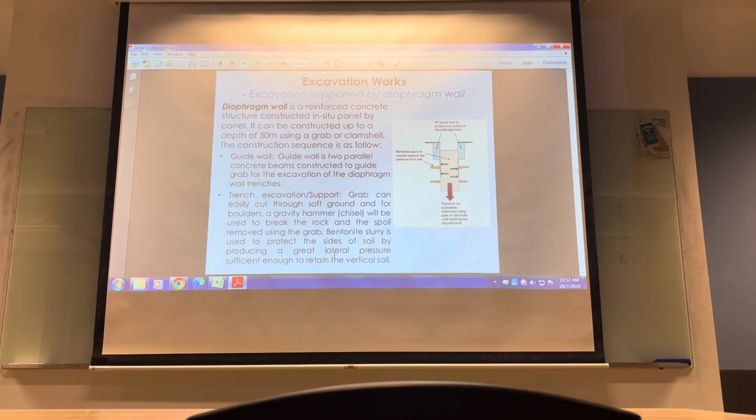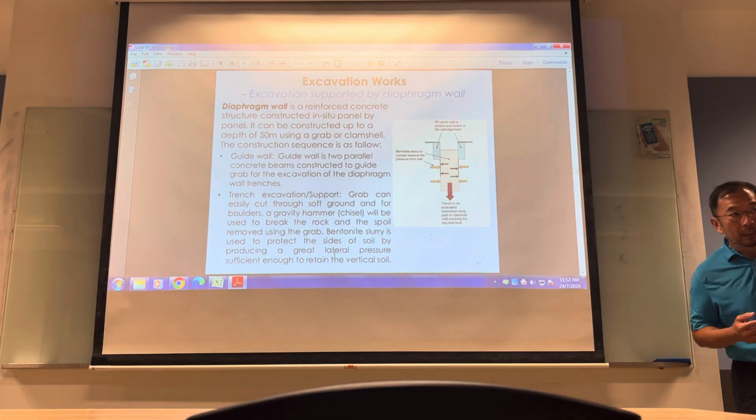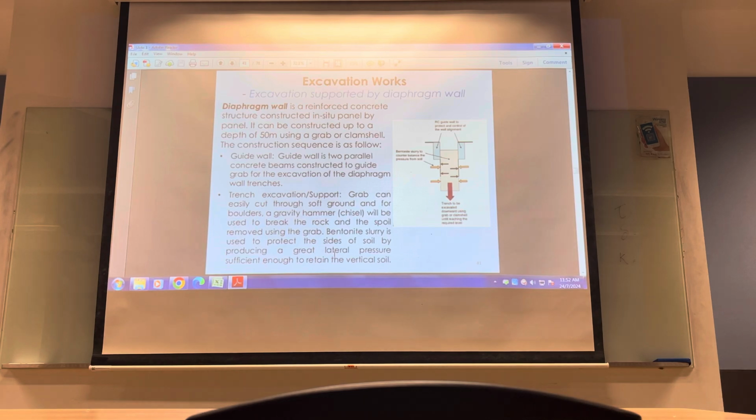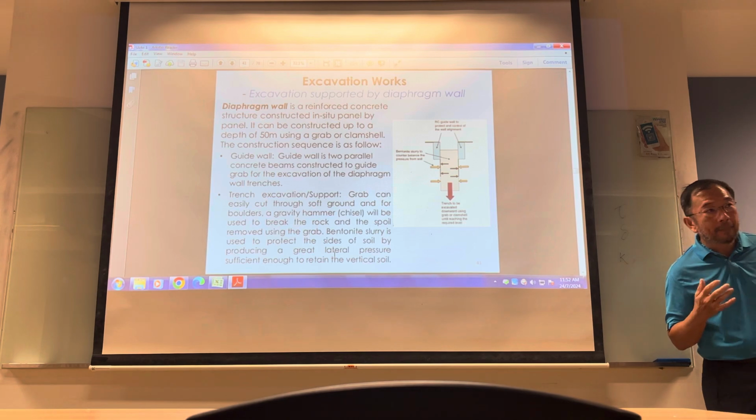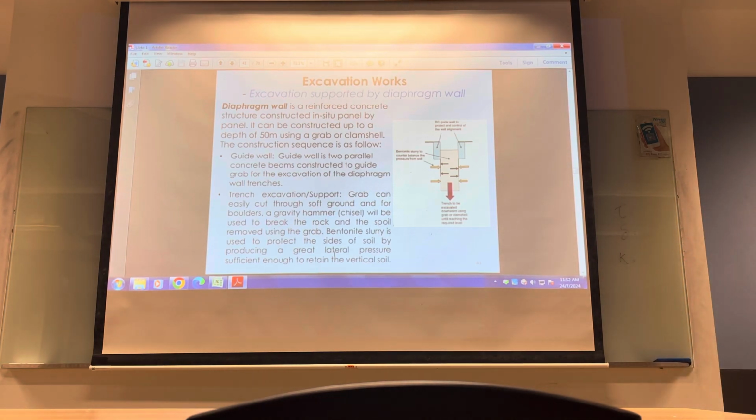Time to install it. Sheet pile fast, diaphragm wall very long. Again, in terms of the 1 to 10 scale, diaphragm wall will take 10 months to complete the perimeter of your excavation, but sheet pile will take about 4 months in that sort of range.